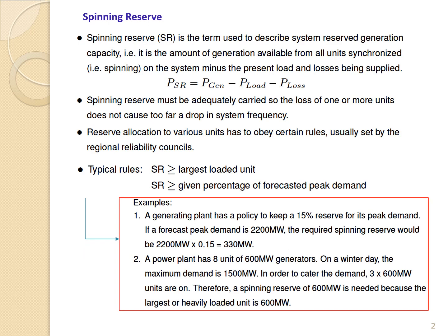commitment. In power systems, there may be a sudden increase of load or a fault on the system or on a generator, or some generator is shut down for maintenance. In such situations, some system capacity has to be kept as reserve, known as spinning reserve, to meet the unexpected increase in the load demand and to ensure the power supply in the event of any generator outage.